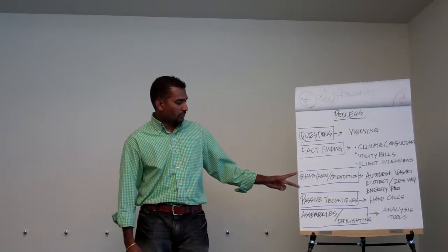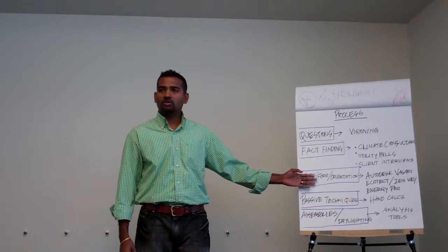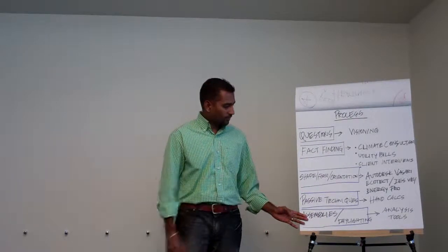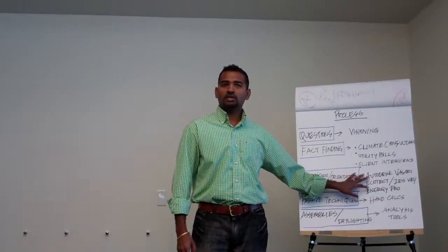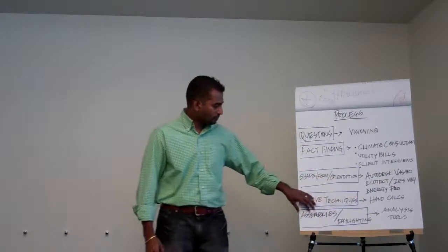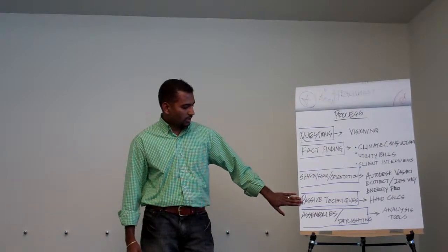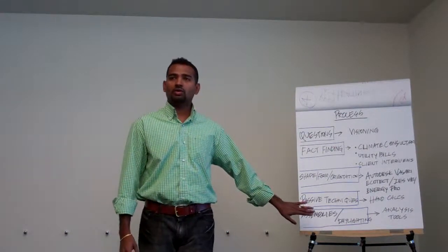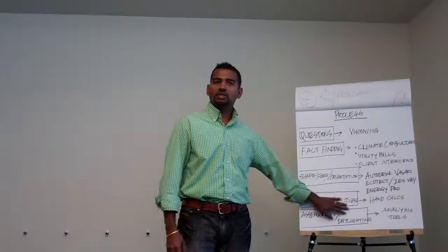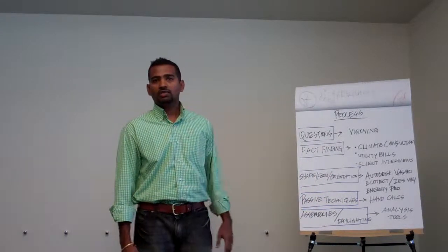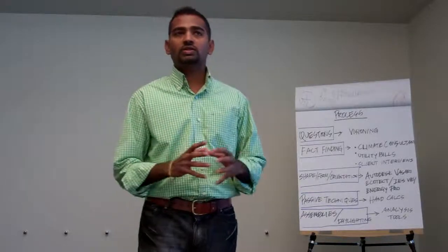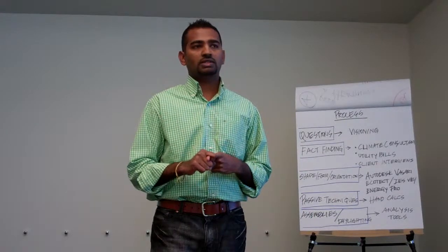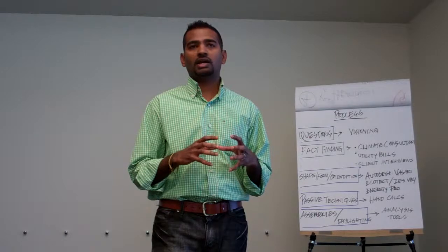Then the next thing to do is to find out the best shape, form, and orientation for your building design based on a baseline that suits your climate. And there are multiple tools that can do this. I'm going to talk about Autodesk Vasari today. And then once you do this, we can explore some passive technologies. Unfortunately, many tools out there today cannot effectively do these passive technologies. For instance, it's very difficult to use Trane TRACE or any of the programs we have to figure out natural ventilation. So you have to rely on hand calcs for now.